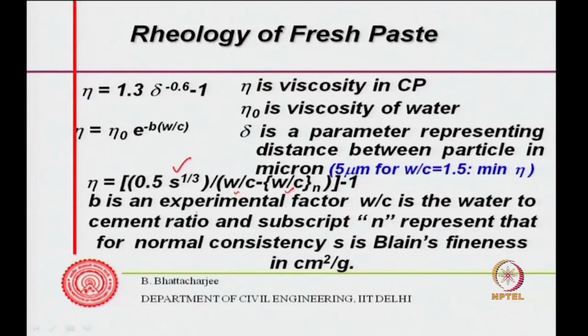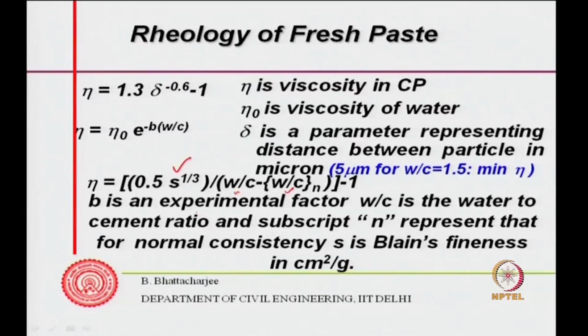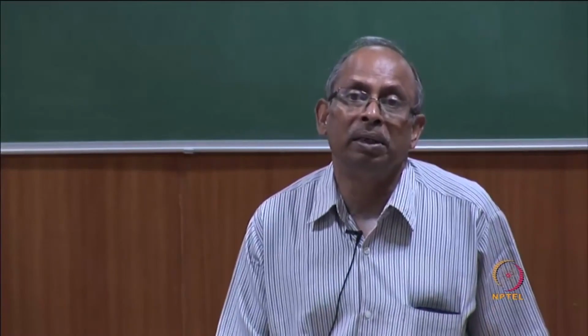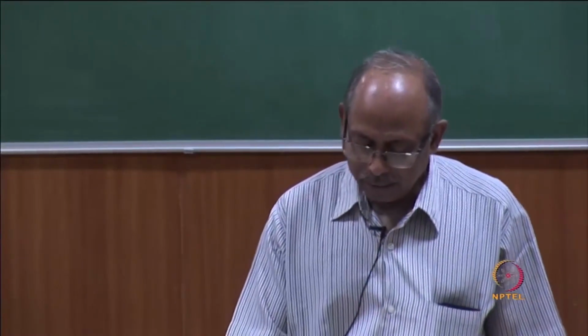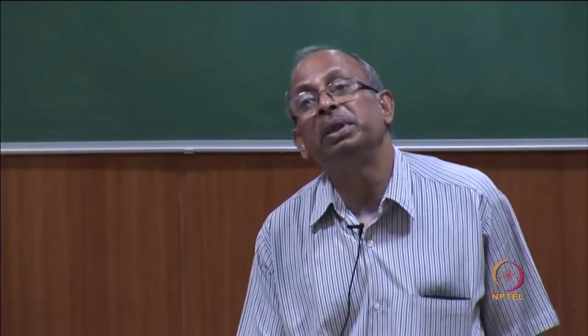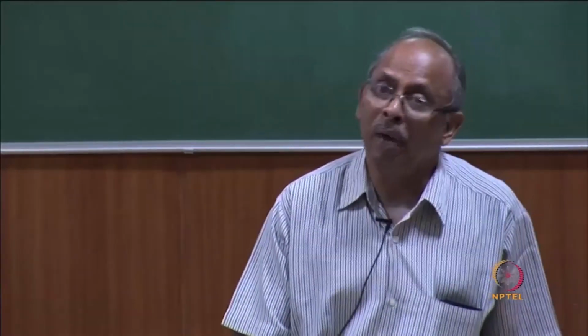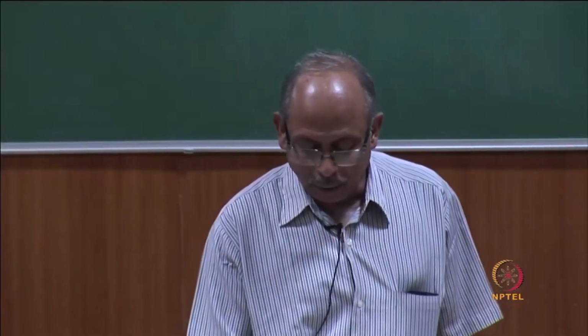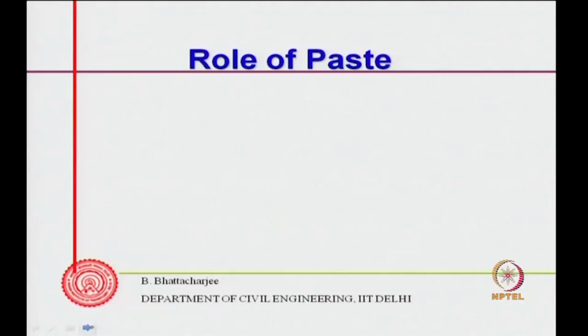So, what we understand is it is related to the type of cement of course, but it is also related to water to cement, but we are talking of the cement paste only. Water to cement, how much is the water in the cementitious, cement water or powder system, that is what governs the viscosity of the paste itself. In case of concrete, it will be the water content vis-a-vis the total mass or volume of the aggregate and concrete system. So, water content is what would govern this viscosity.